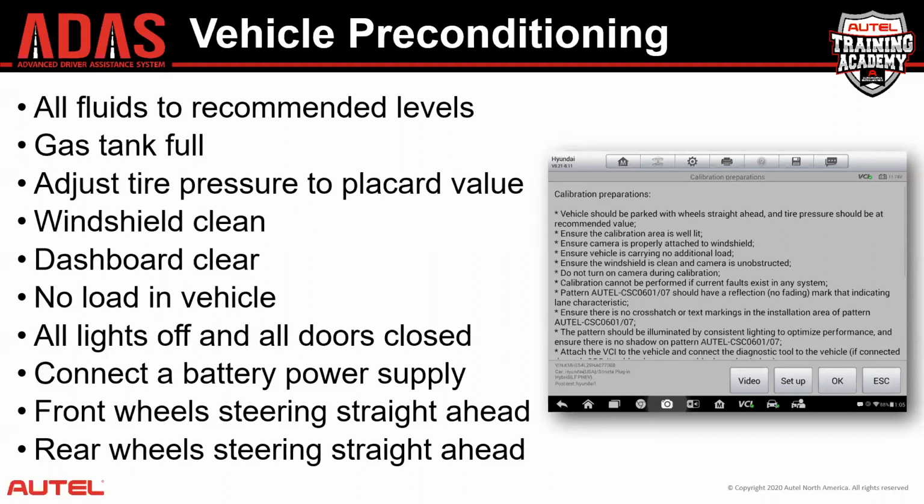Ensure all the lights are off and the doors are closed. You want the lights off for a couple of reasons. One, you don't want to drain the battery. Two, you don't want headlights or driving lights shining on your calibration target that, again, may wash out some of the blacks, and the vehicle camera may not be able to properly identify the contrast between black and white.